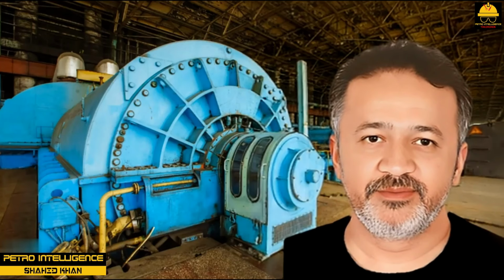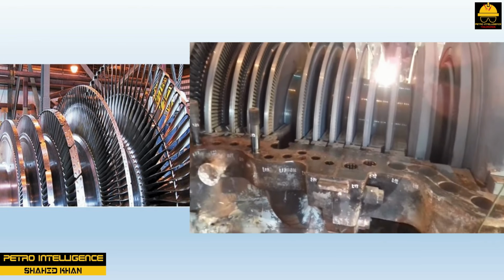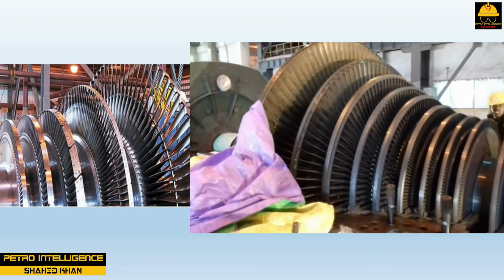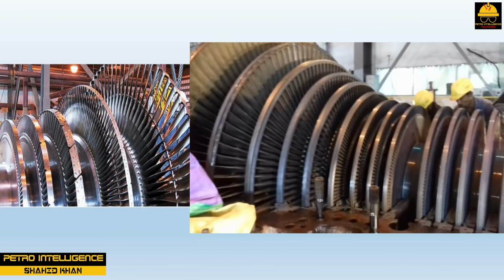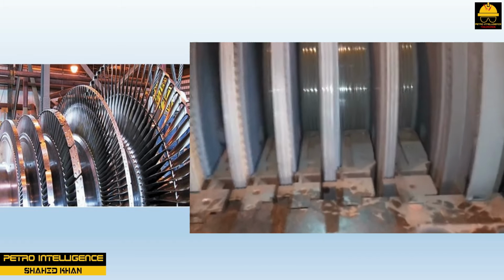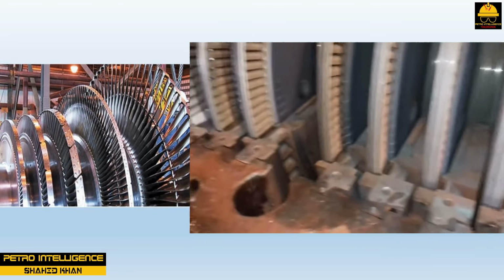Fixed blades. The fixed blades, as shown in the picture, are made of durable stainless steel that has been rolled and drawn. The fixed blades are a half-moon-shaped ring located in the lower section of the turbine, sandwiched between the moving blades. When fixed and rotating blades are aligned in the correct position, steam passages are formed across the wheel of the turbine.